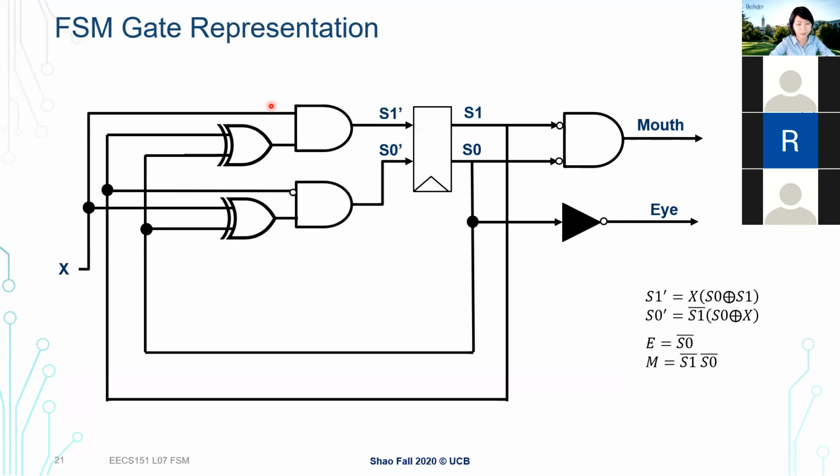In this simplified example, we actually don't have an initial state or a reset signal. Typically, you always have a reset signal and also an initial state, which describes to your circuit what the initial values should be. In this example, there should actually be an initial state, and we should take the reset signal as another input, instead of just the external input.